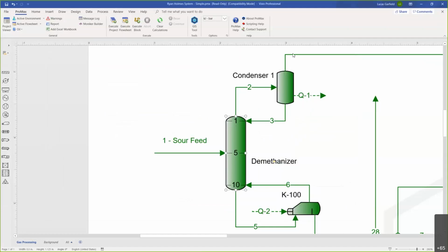If I look at the overhead, I'm at negative 90 degrees Celsius. So that's colder than the feed. And here's my question. Think about this. Can you anticipate there being a potential problem with operating at cryogenic temperatures when CO2 is present? What if dry ice forms? I mean, CO2 can solidify, right?